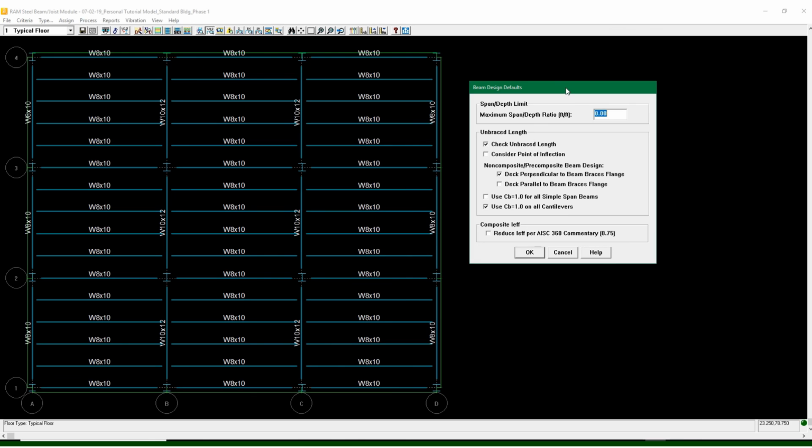I typically like to use something as far as, for every foot of span, I would recommend having at least, I would say at least 0.7 inches, if you will, almost 3/4 of an inch for every foot of span. You can go lower than that. Go to 0.6. You could go much lower and it still works.